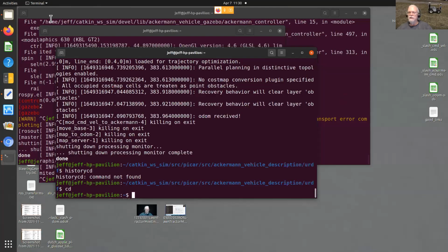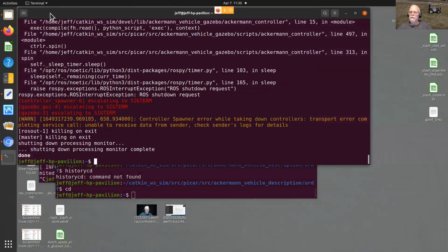The one in the back is going to start up the simulator, and it also starts the Ackerman converter. That's a Python script. You feed it an Ackerman command, and then it sends the values to the simulator to move your wheels, to both turn the wheels for forward and backward motion and control the steering.